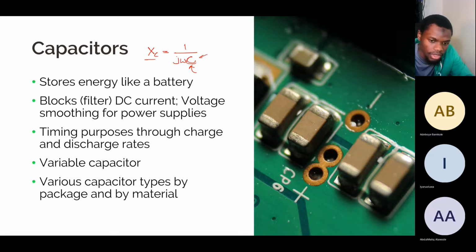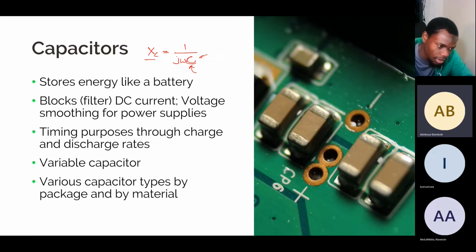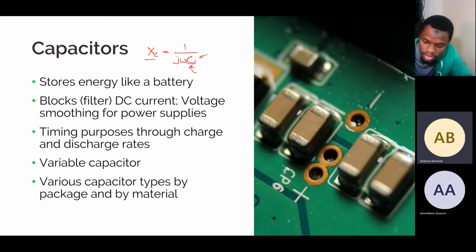Also, there are different types of capacitor packages and different types of capacitors that have different advantages over each other depending on what application you are focusing on. So we have Mylar capacitors, and what I've learned is some capacitors are very good at high frequencies and some are not. So if you are designing something in the gigahertz or megahertz range, there's a specific type of capacitor you want to use. Just like I mentioned earlier, this book explains a lot of that stuff.